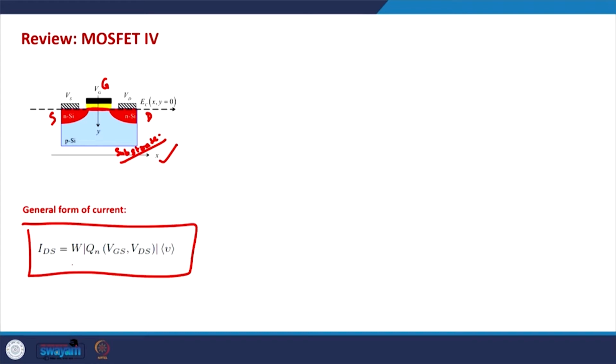IDS, the current from drain to source, essentially depends on two factors. One is the charge in the channel, Qn(VGS, VDS). This charge Qn depends both on VGS and VDS, and it depends on the velocity at which this charge is moved across the channel, which I would say is a quite intuitive definition of the current.